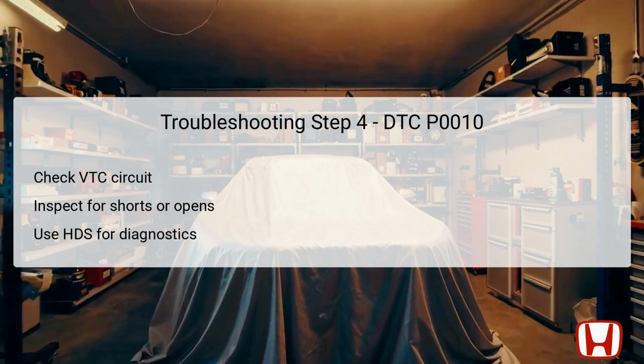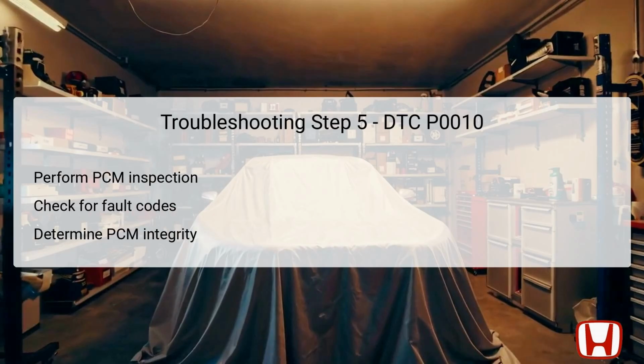Performing these checks with the Honda Diagnostic System makes it easier to identify any faults that may not be visible through physical inspection alone. The final troubleshooting step involves the PCM inspection. At this stage, it is necessary to determine whether the remaining functions of the PCM are operating correctly after previous checks have validated that the VTC oil control solenoid and its circuit are in good condition. Consult the diagnostic readout for any fault codes.